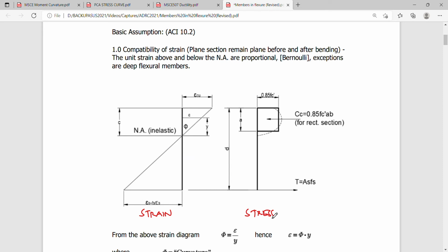Okay, so to start with, we have to know what strain is all about. Why is it that this is represented by an alternate strain measurement on either side? The reason is that flexural behavior introduces a reversed type of stress, which is positive on one side and negative on the other side, or vice versa. So this is just the compression side and the tension side.